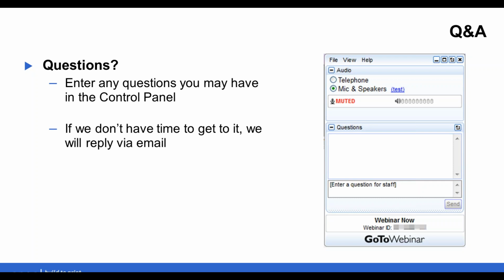Chem film would be MIL-DTL-5541. We'd recommend Class 3 there since it's a conductive class. Class 1A is obviously best for corrosion, but won't give you the electrical properties you need. So if your application will allow, you can also eliminate the prime and paint operation and just apply chem film per Class 3 to the entire aluminum structure.